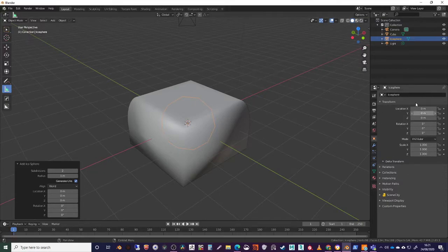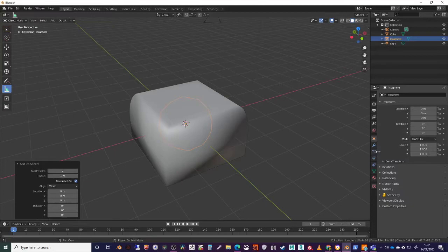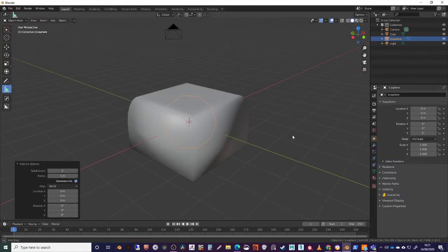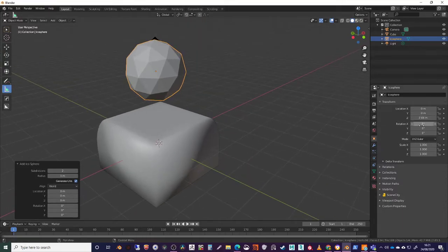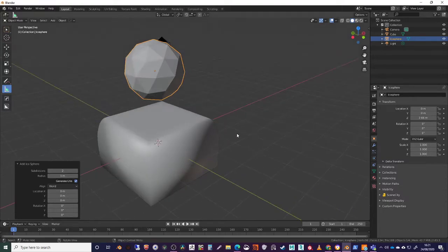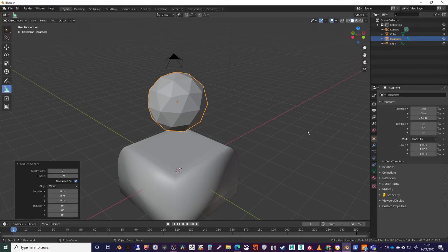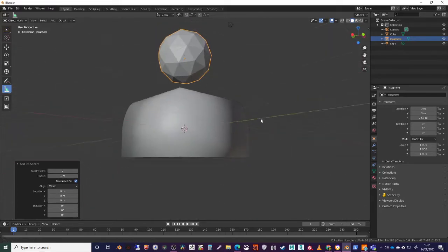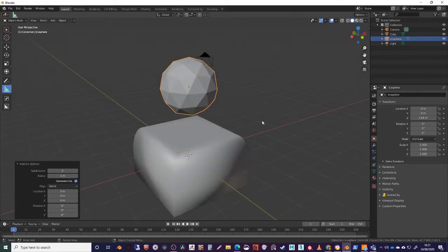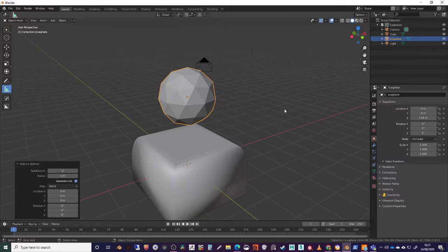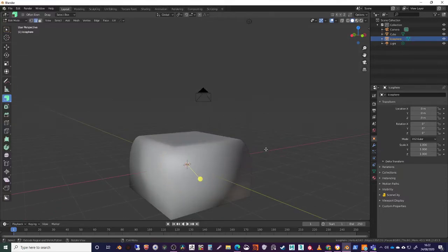So one thing to remember is we've got the transform tools here. This would be like our outliner window, and this is coming under the object properties. If I actually just grab this and move this up, then we're moving up 2.6 meters. And if I do any scaling or anything, I have to be careful because the scaling does affect some of the modifiers. So you will find a lot of tutorials advise, because the pivot position's gone with the object, and because of Blender 2.7 and less, whatever they were, that a lot of tutorials will go into edit mode.